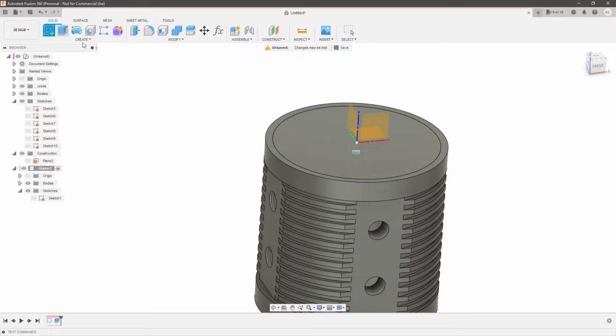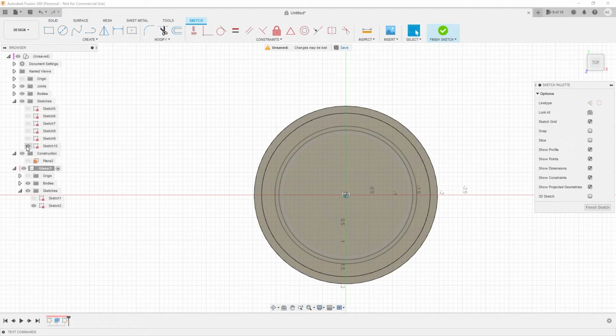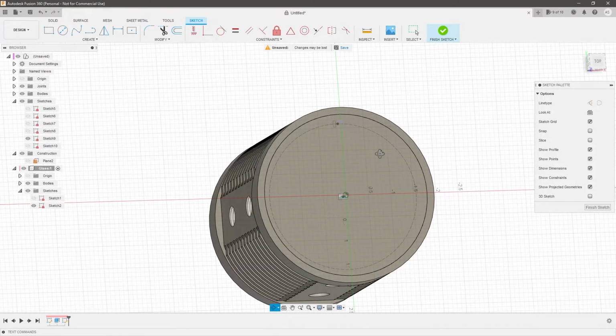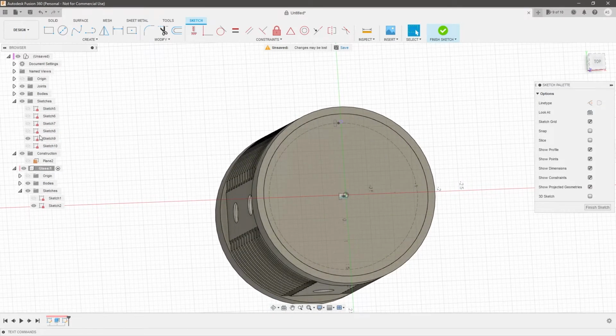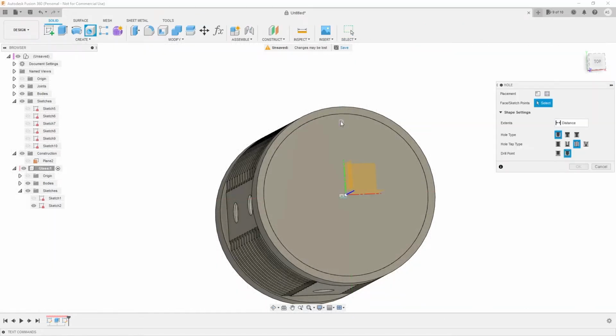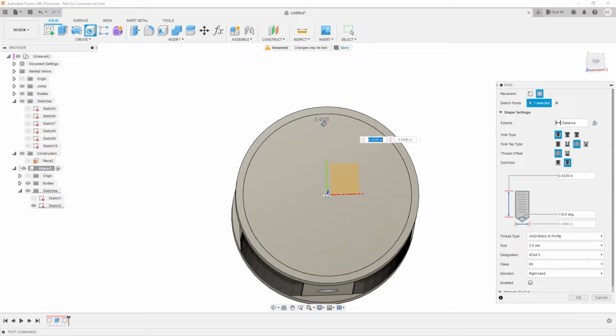And then we're going to go ahead and sketch on that top surface, and we're going to project in that little point right here to that top surface, because that gives us our center point of our first circle from the previous bolt pattern. So now I can go ahead and create a hole on that point, and then we'll do another circular pattern wrapping around. In this case, we don't want a counterbore or a countersink, although we could do countersink. We can just go ahead and do a simple hole.